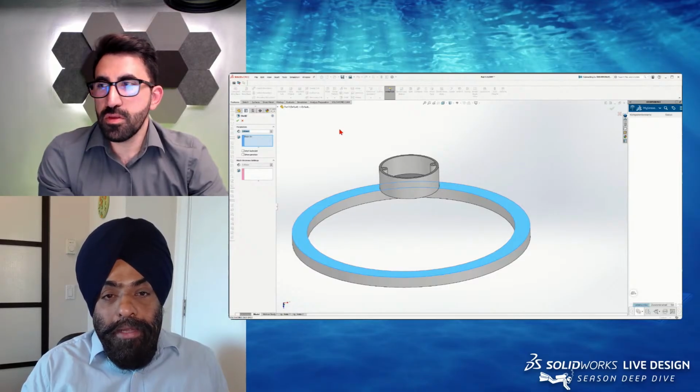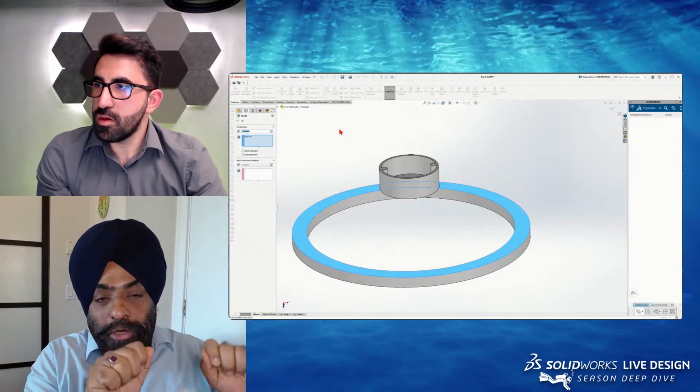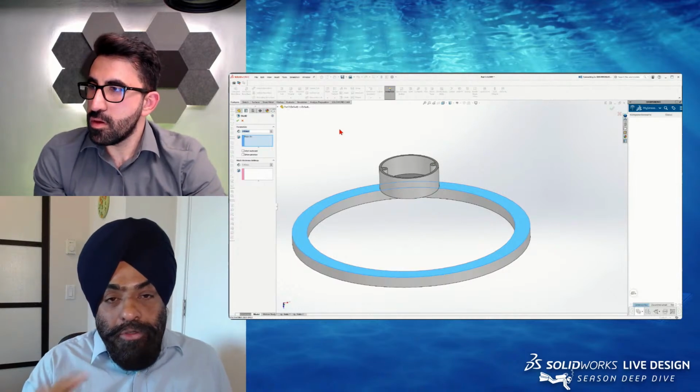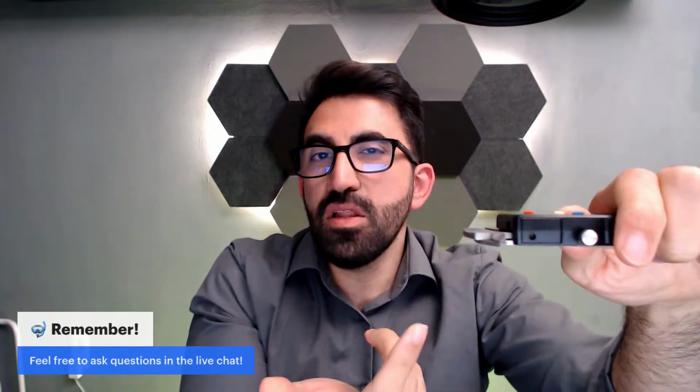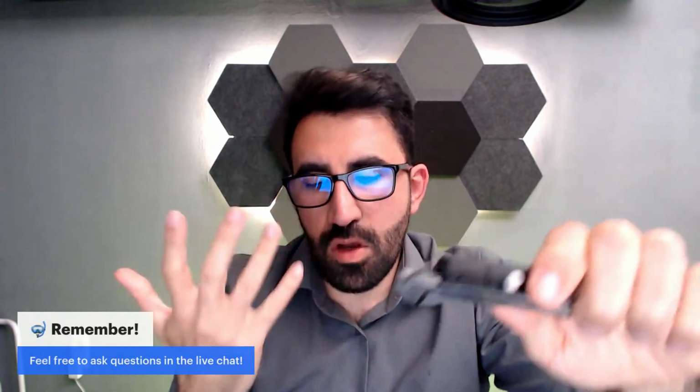If I 3D print, Aryan, can you move it to the top camera, because it seems the overhead is not. Yeah, so this is 1 millimeter, right? And this is super tiny. If you look at it, if I 3D print a component that is so thin, obviously it's going to break very soon. So what if we do three? Something like this. It's a lot more robust and stronger, so I'm going to go with that.